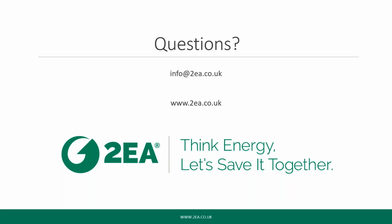Absolutely. And the other thing you should always take into consideration is that technology moves on. When I first started looking at CHPs, we were looking at 30 to 32% electrical efficiency. Now these are anywhere between 35 and 38%. So as technology moves on, you may wish to update your CHP unit or replace it entirely, and this can be included within the maintenance package.